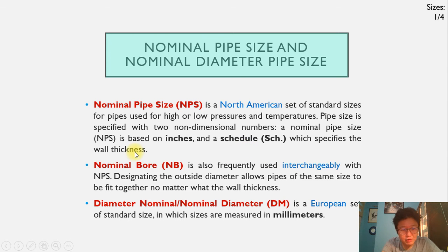Remember, at the beginning of this video recording, we mentioned that to describe a pipe or to tell the size of a pipe, we'll talk about the internal diameter or the nominal diameter, and we need to know the thickness as well, because two pipes may have the same nominal diameter or internal diameter, but because of the different wall thickness, then that would affect the subsequent design in terms of the fittings and the connections.